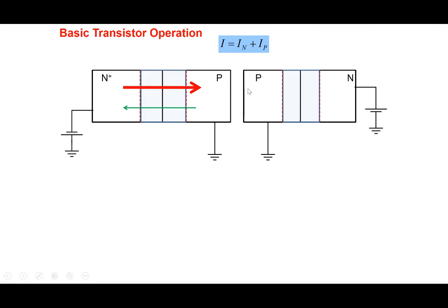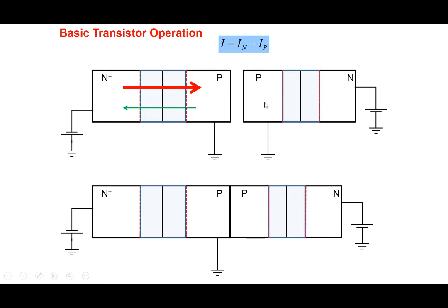Okay. All right, so we have these two junctions, and this is what is happening in the forward bias junction, and this is what is happening in the reverse bias junction. Now let's bring the two junctions together. Let's fuse them together here. When you fuse them together, these electrons which have come into the P region, note that when you forward bias it, a lot of electrons come into the P region. And now these electrons that have come into the P region can then go to the other junction here. They can go like this.